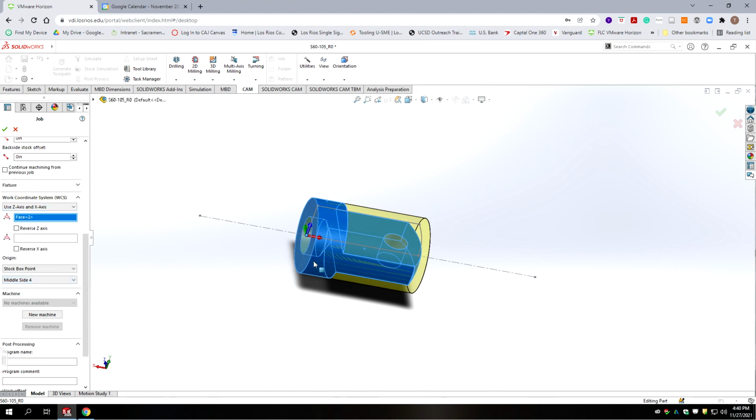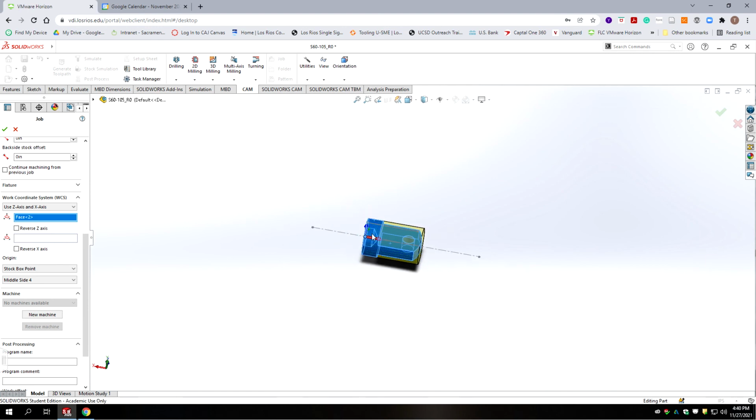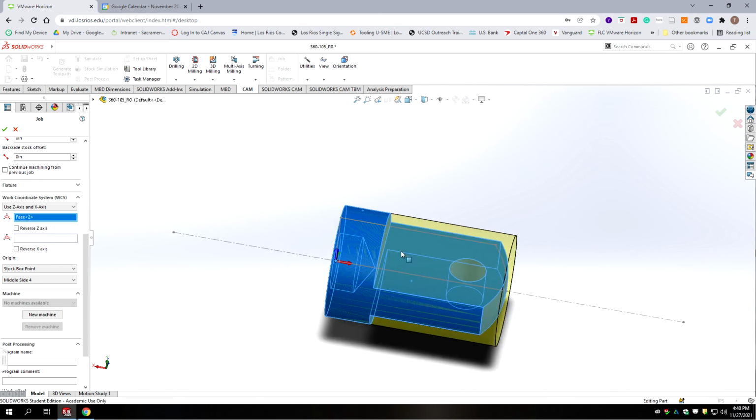So if we held this in what's called a collet, there's a tool that goes inside a collet called a collet stop, which will allow you to register the part, and you would be gripping on the diameter here, and the stop would hit this face, or I guess I could hit the bottom of the hole, but being that all the dimensions come off of this edge, you would want to use that as your registration point.